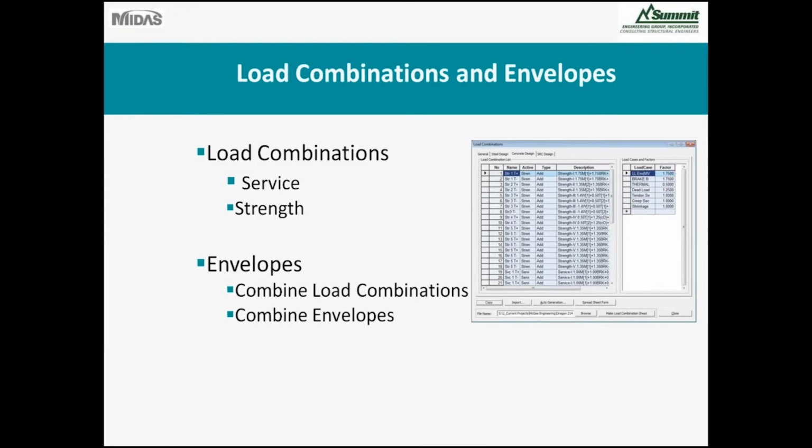For the load combinations, I did load combinations for both strength and service to check service stresses throughout the construction stages, and then also check ultimate strength. I set all these load combinations up in MIDAS, and then also combined the combinations into envelopes.